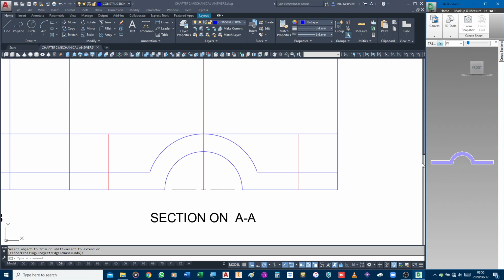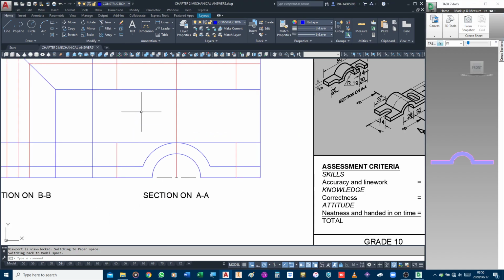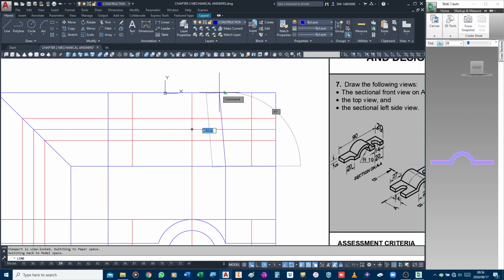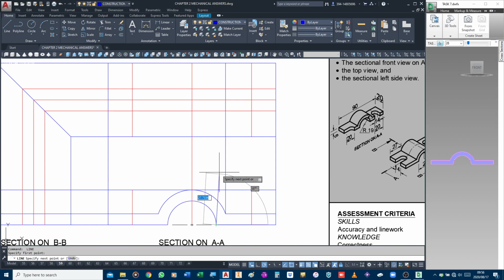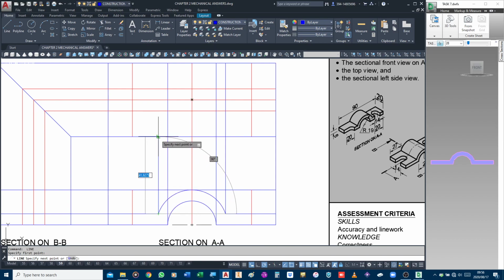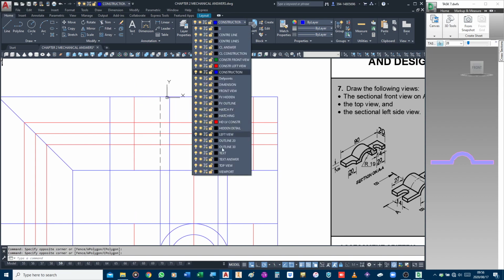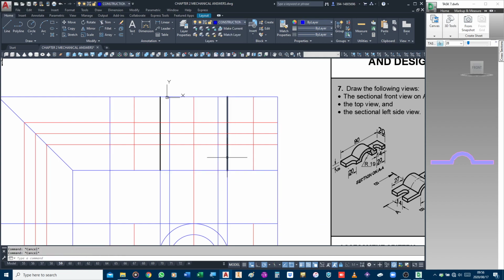Okay, so I hope all of you agree with that. That's what I've got here set up so far. But now I need to look at these grooves. But before that, let's just take this geometry that I've drawn and draw it in the top view. So from there to there, I've got these lines. And if you now look at it, this line that I'm working with will not be a solid line. It will be a hidden line. So this line here and this line here will be a solid line. This line here and this line here will be a hidden line.